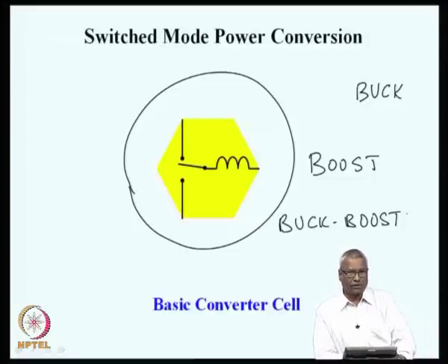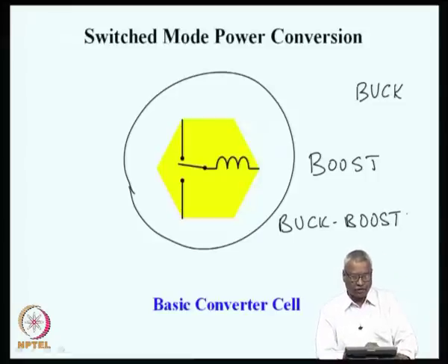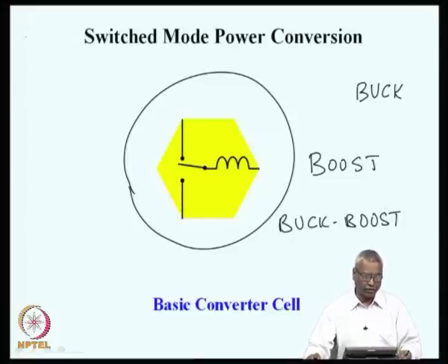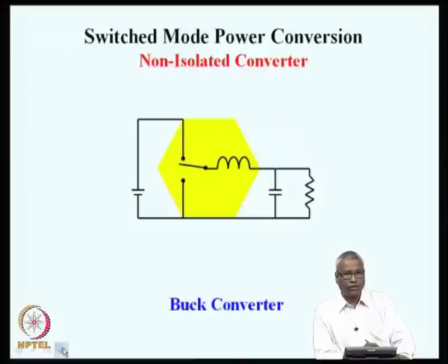So, all these power converters were providing power from a source to a load with the ground potential, the zero potential, which is common for the source as well as the load. So, such converters were called the non-isolated power converters, and this is a non-isolated buck converter, and we saw the variations of boost converter and flyback converter, all belonging to the non-isolated family of power converters.